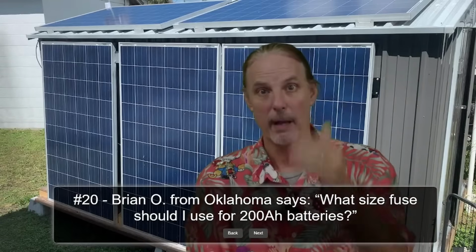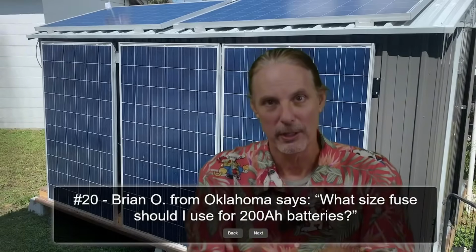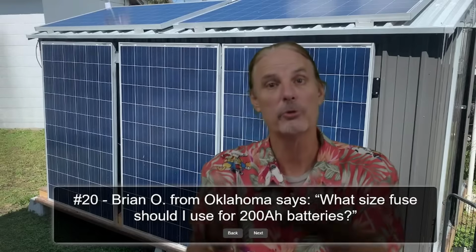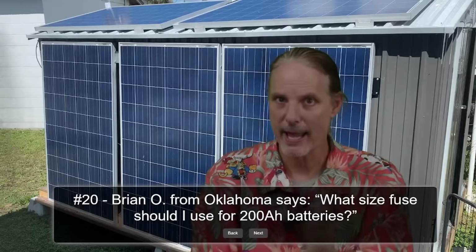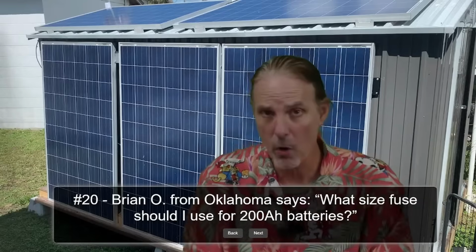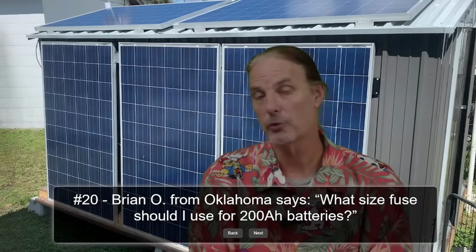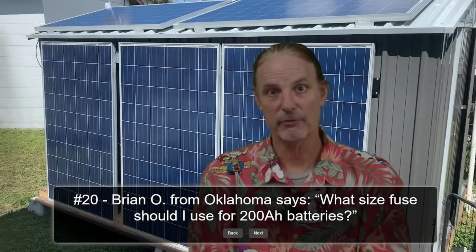I had 100 amp batteries. I assumed that two of them could go off, leaving me with a 200 amp maximum pull. So I put in a 250 amp fuse. If you have a 100 amp BMS and you only have one, then you will want to do 20% of that, being a 120 amp fuse. And that would prevent it from overcharge there.